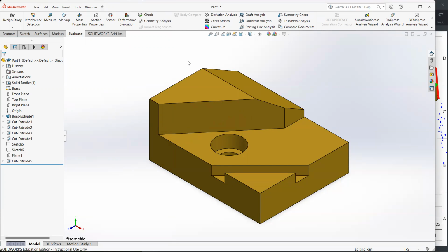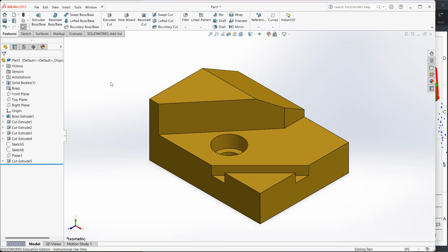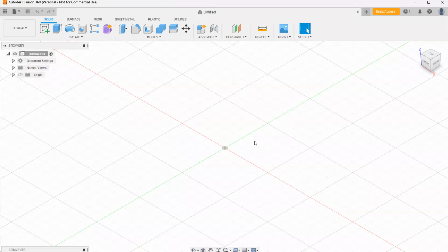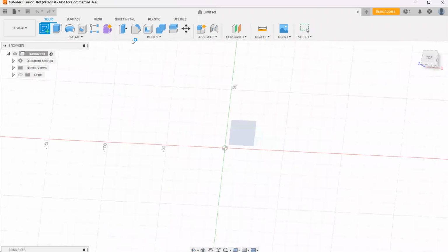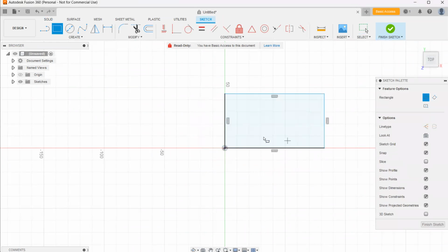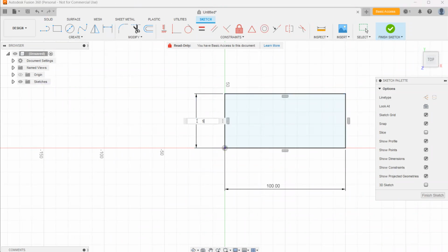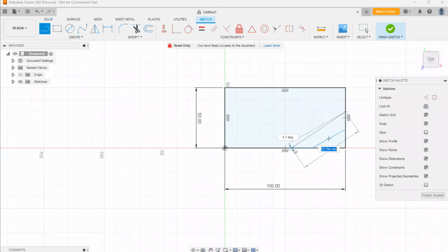And in this class only, for those who do not have SolidWorks but would like to follow this, the same commands and features are also available in other CAD software, as I explained in the first class. So just for now, we could see that we could do the same thing in Fusion 360. Here, for example, we could have a sketch. We could use this to draw the different dimensions that we would like. We could also dimension it. For example, here 150.